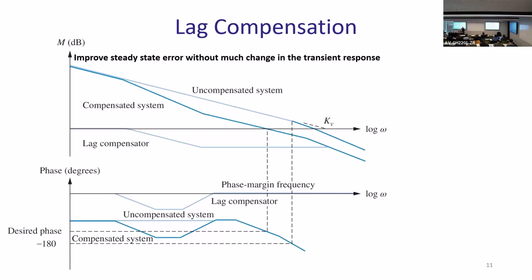So the idea is that you want your controller poles and zeros to be far to the left, at least a decade to the left. That will be somewhere here that will not even affect that region at all in terms of phase. So phase here is your original phase practically. Okay, so you're not changing anything in the phase. And then what happens is that if you're not changing that phase in the neighborhood where the phase margins that you want, you have it, okay? You're doing previous procedure the same way exactly.